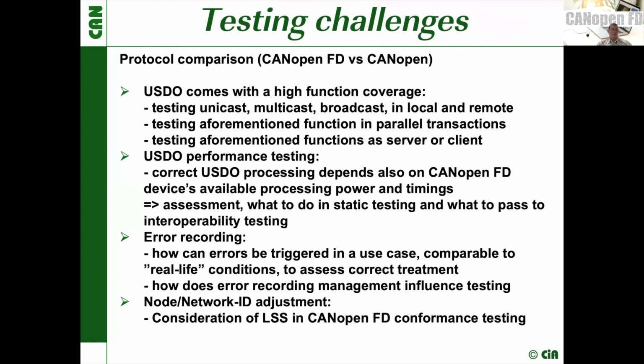Of course, we see with CANopen FD some testing challenges. You know, the USDO is a very comprehensive tool in embedded networking. There's a high function coverage. So you can assume testing unicast, multicast, broadcast in a local and remote way, testing these functions in parallel transactions, and furthermore, not only from a server, but also from a client perspective. So they're rather challenging things, which exceed having just one tool and one test candidate, but you need an entire test environment with several devices.